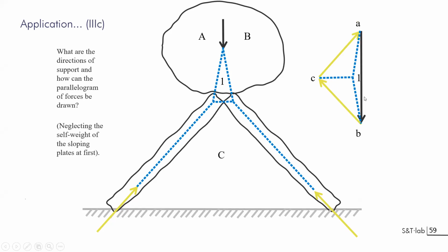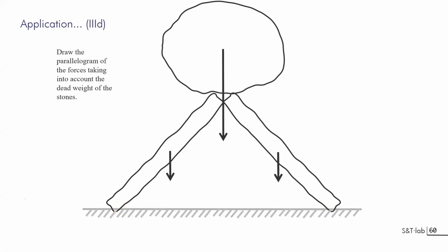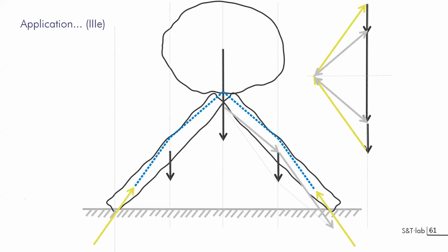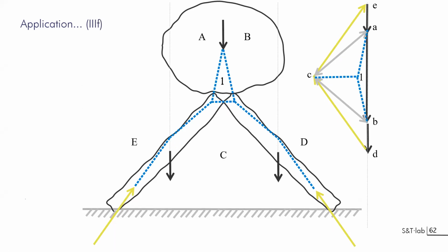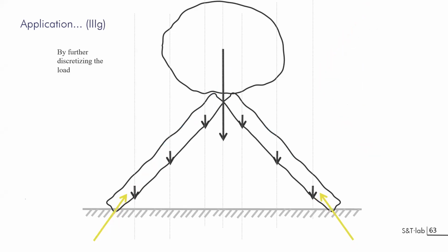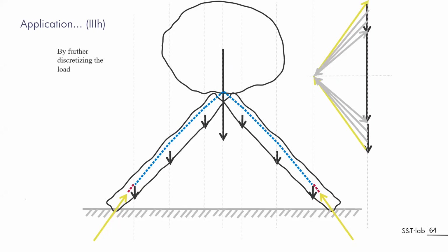Going ahead, if you are just not going outside of the stone, you have to be more precise about the way that thing will be designed here, and you see the force polygon getting more and more complex. I can go ahead with this using the weight from the supporting stone and having the same kind of resolution. I can also do the same with progressively splitting the weight into its components to have the first arches that will be appearing on the system, and that will drive you to the principle of funicular polygons, as we can see later on.